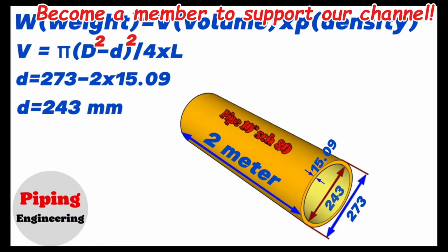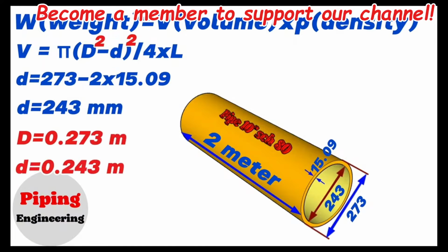These dimensions should be converted to meters, because in the density charts of ferrous metals they use meters. Then, the outside diameter of the 10-inch pipe in our example is 0.273 meters and the inside diameter is 0.243 meters. We also know that the length of the pipe is 2 meters.